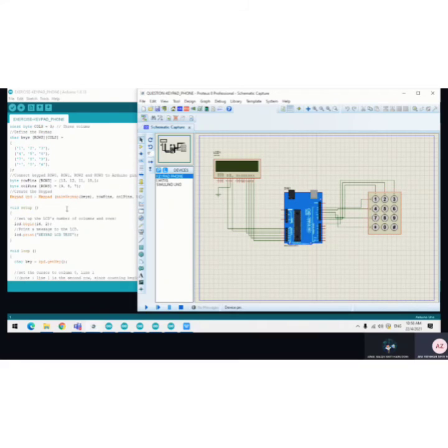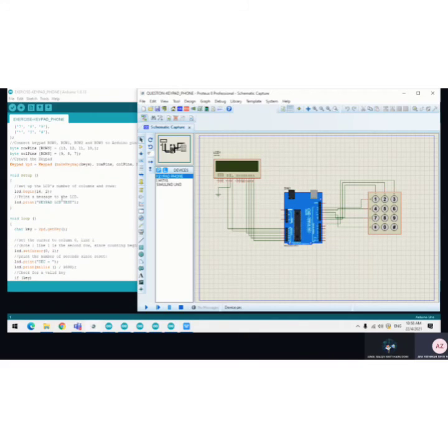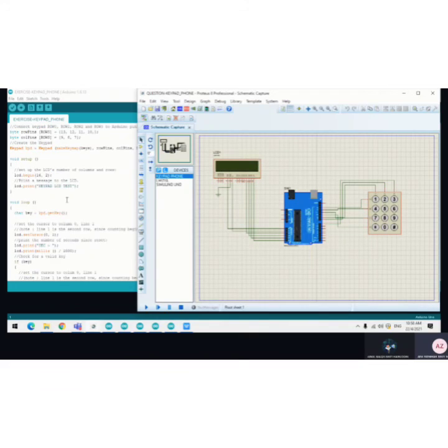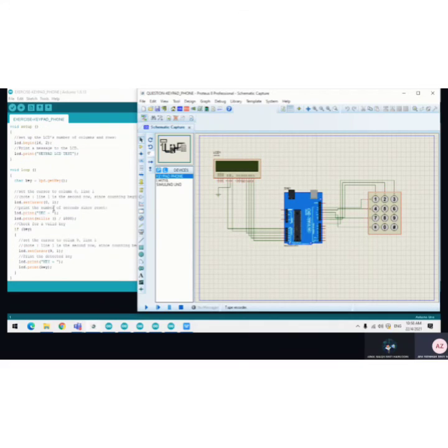And then on the board setup, LCD begin. This is LCD begin for 16x2. And on the LCD, we display the message keypad LCD test, and we have to set cursor 0,1 to print how many seconds it shows when we press the button.